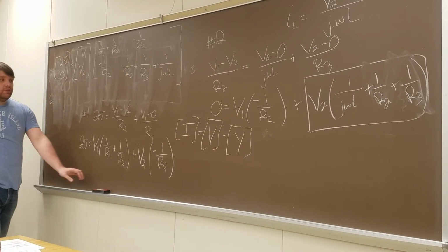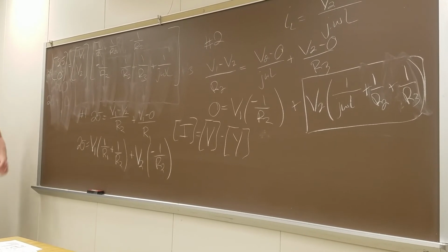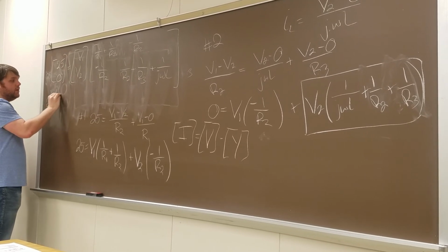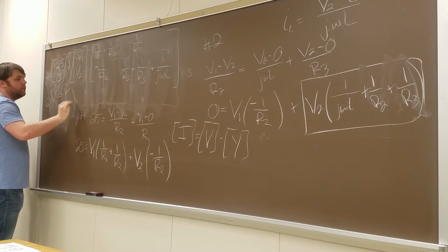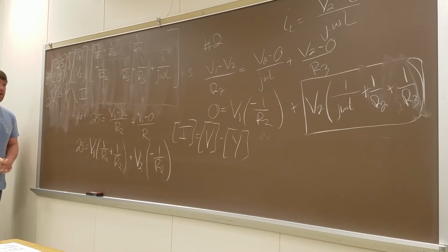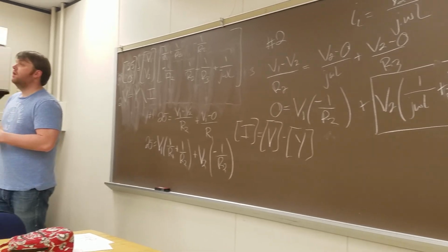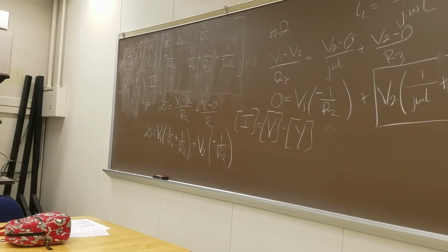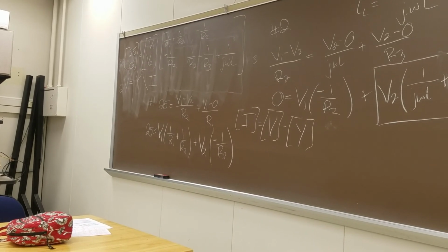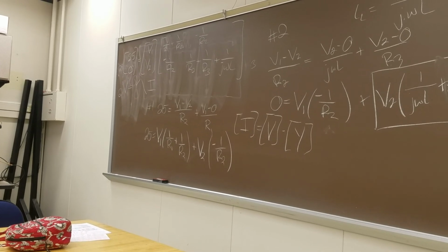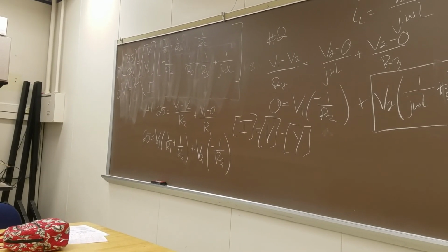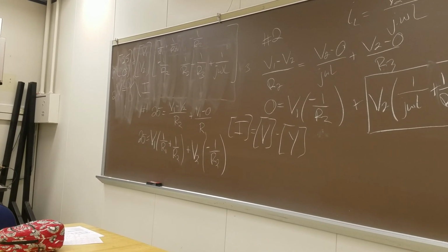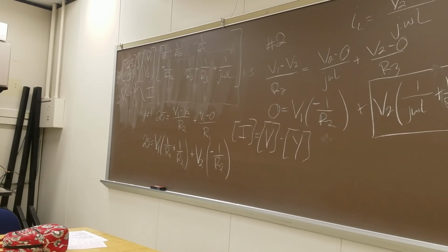This is now in a state, once you've actually plugged in numbers, where it is very solvable in MATLAB. What you'll do is, once you've defined your variables, V is equal to Y, backwards division, your current. And that will output nodal voltages for you. Those nodal voltages are going to be in the form of A plus j times B. So it will be your job to convert back to a phasor, and then convert that phasor back to a cosine based off of the omega value that we have. Okay? That's how most of the homework problems are in this section. It's something similar to this, if we're dealing with frequency. You can break them all down kind of like this.